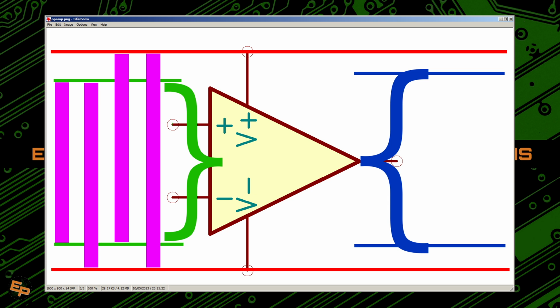But the idea is that when a transistor saturates, it apparently tends to get stuck for a short while in that state, and if we want to switch it from being saturated into the linear region or back into blocking, well, it's gonna take a bit of time. Not a lot, but sometimes it's significant.